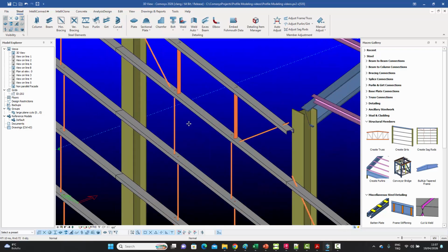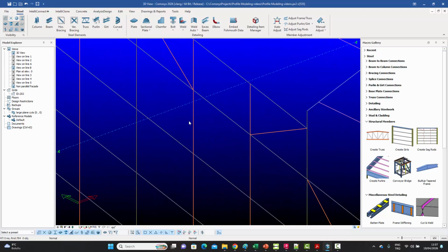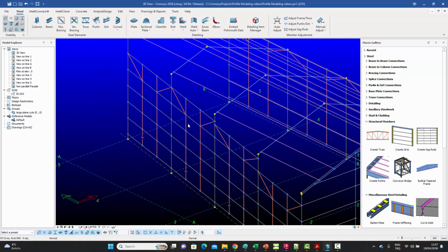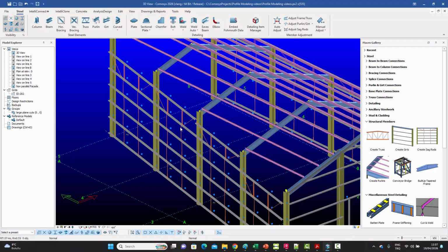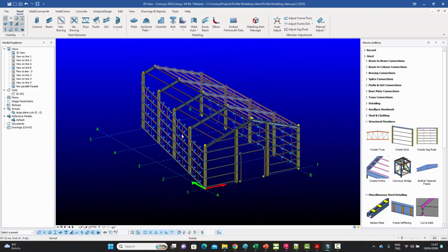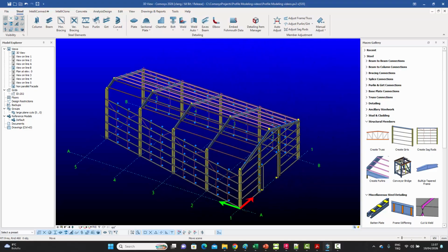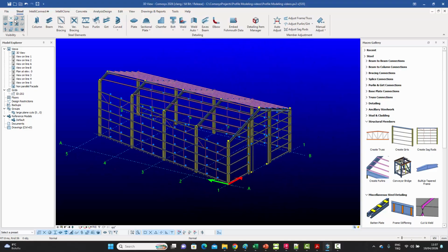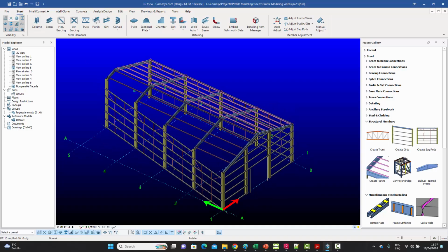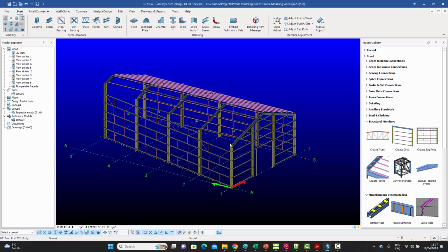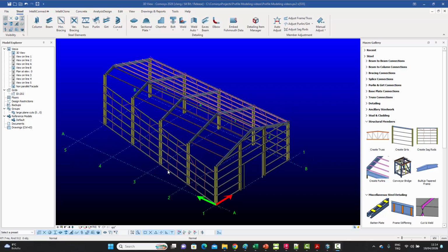All these, once again, if you turn on the Alt T, you can see that they're all entered in the line mode correctly. The finite element definition lines are correct. So what we did in perhaps 5-7 minutes, we managed to do in 5-7 seconds. But it's a good idea to always work manually in the beginning, so that you know exactly how to get these things done, just in case a macro is not available.